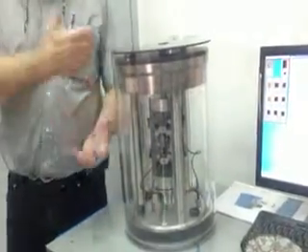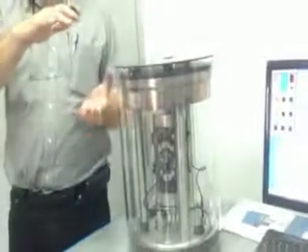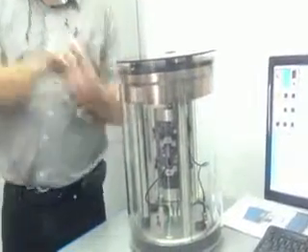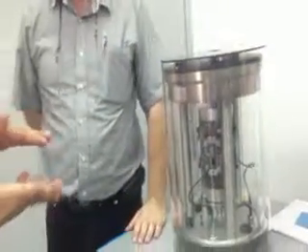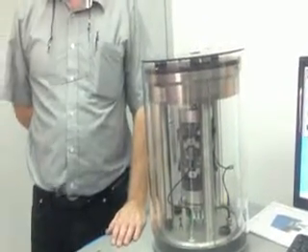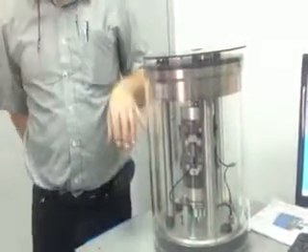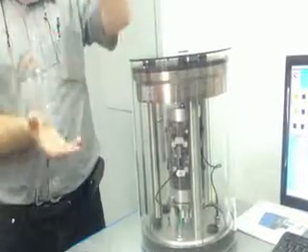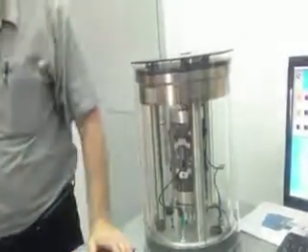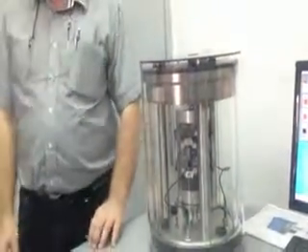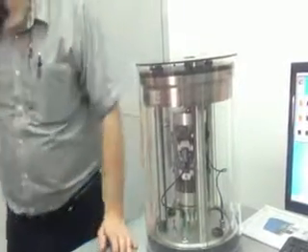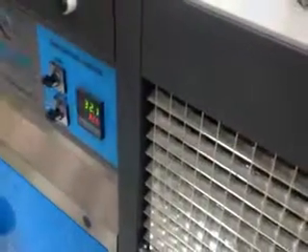You would start with the cooler temperatures first, because you run those tests, take the sample out, put it back in the oven, and take it up to the next temperature. For example, we will start at minus 4 or something, up to 60 degrees. You do that because you're trying to keep the sample in its elastic region. So we will enter a low temperature and a high temperature, for example 4 for the low, and 60 or 50 for the high. It is managed automatically; the chamber will adjust.